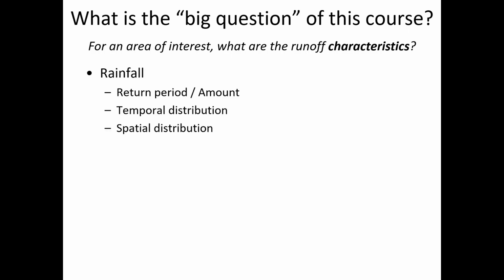So the input data that we have to account for is the rainfall. And we've talked about how there can be both variability in the timing of rainfall and also spatial variability. So in the previous lectures, we talked about, just as an example, how a hydrograph could be different if a storm was coming from the north and headed southward versus if a storm was headed from the south of a watershed northward. And how if the direction of the drainage is matched by the direction of the storm, you could have more of the flow arrive at the same time, even if the storm depth is the same.